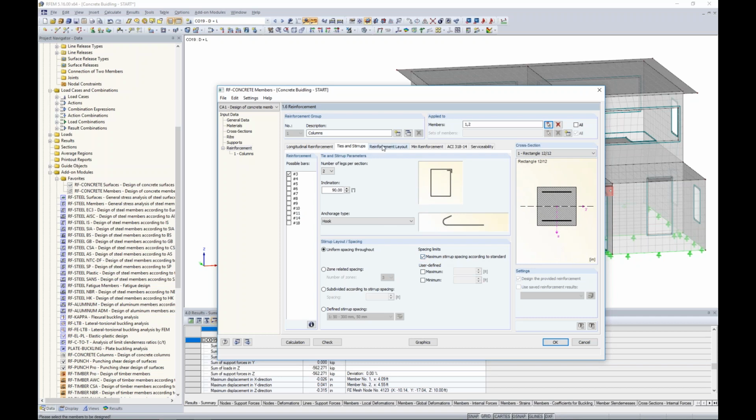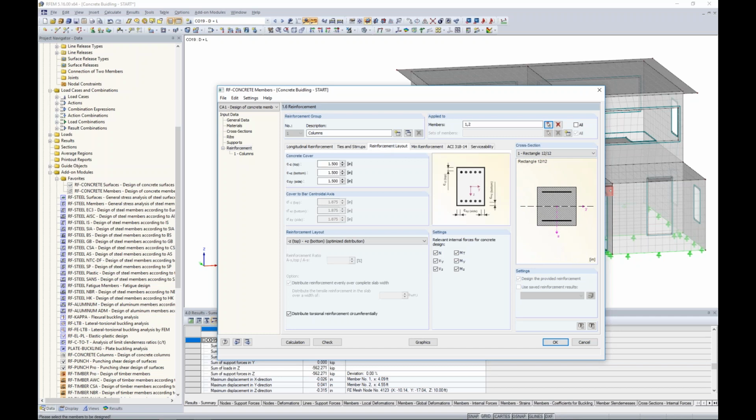the ACI. The reinforcement layout, the first thing to set here is the concrete cover. The ACI standard refers to table 26.13.1 for concrete designation, and for number 5s or smaller that are exposed to weather, the code tells us that 1.5 inches is adequate. So assuming we're using number 5s here, we'll just keep this as the default of 1.5 inches. If the program came up with number 6s for my reinforcement, well, maybe I'd want to go back and adjust this to something more like 2 inches.